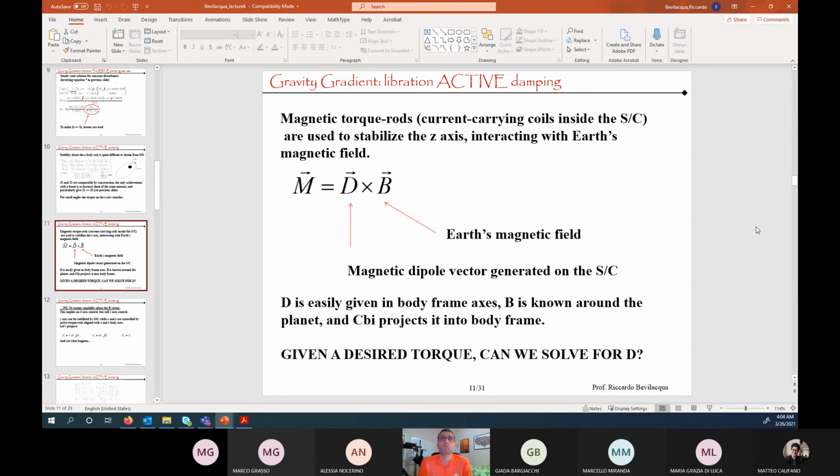And so this is obviously only usable when you're in relatively low Earth orbit. As you go up, the magnetic field intensity of the Earth, which in this equation is B, vanishes, and you need to have a planet with a magnetic field. Otherwise, it doesn't work. So around Mars, for example, there's almost no magnetic field, so you really can't use this. And so if you want to, for example, detumble a spacecraft deployed around Mars, you have to use some other means, definitely not the standard magnetic moment that we use around the Earth.